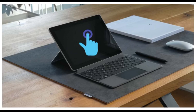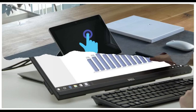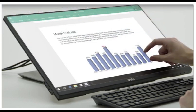A capacitive touch screen panel is coated with a material that stores electrical charges. When the display panel is touched, it draws a small amount of charge to the point of contact. Circuits located at each corner of the panel measure the charge and send the information to the controller for processing. Users must touch capacitive touch screen panels with a finger, unlike resistive and surface wave panels that can accommodate a finger or a stylus. Capacitive touch screens are not affected by outside elements and have high clarity.